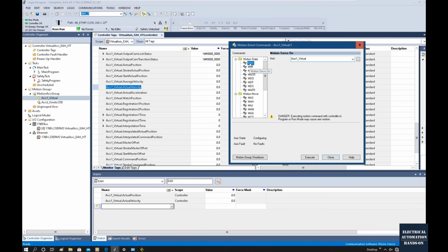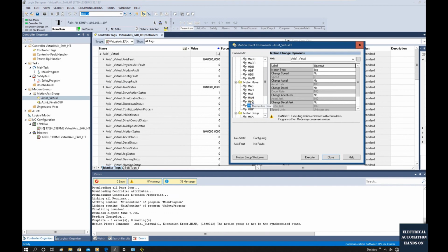For example, we need to verify the drive direction, if forward is the actual forward direction. Also, we need to verify the speed setting, for example, 300 millimeters per second, whether the actual object can run at this velocity. So this is a very commonly used tool to verify our hardware and our entire control system.